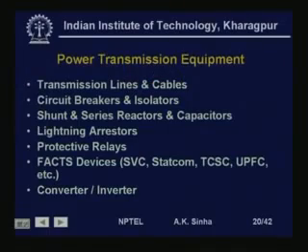We have other devices like shunt and series reactors and capacitors. Reactors are basically reactive power consuming devices, whereas capacitors generate reactive power. So, in order to maintain the voltage profile in the system, we put these capacitors and reactors at various places in the system. Lightning arrestor is one device which is used in